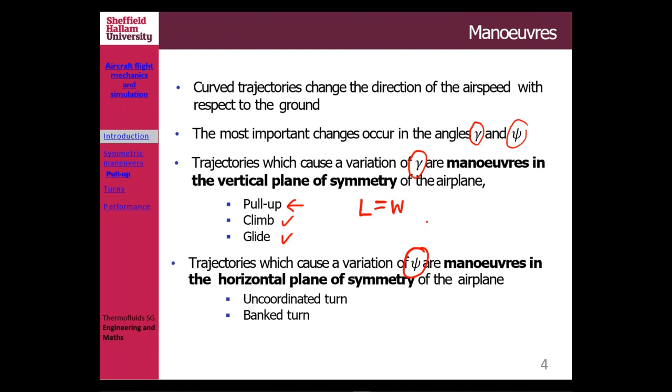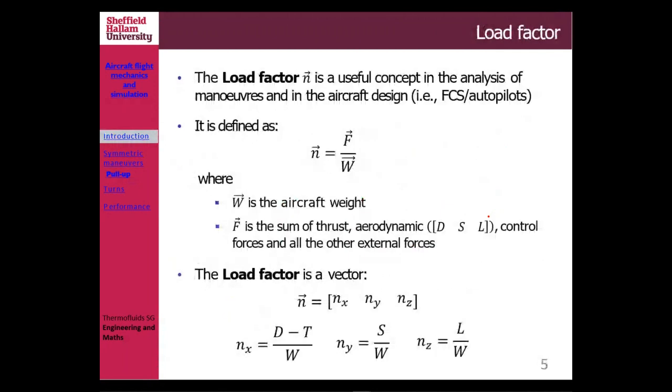So now we could consider that if we want to make sure the lift equals the weight, like in steady level flight, we could consider a factor for that, which we call n in this case. So I have to make sure that n is there in order to make sure that my lift could carry my aircraft, which obviously consists of its weight, right? That is what then comes to the term called load factor.